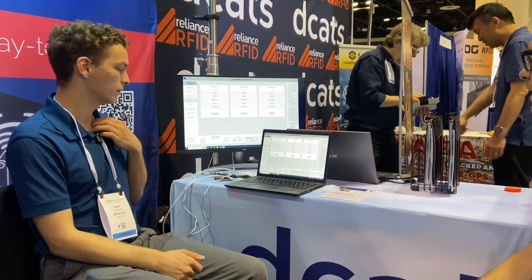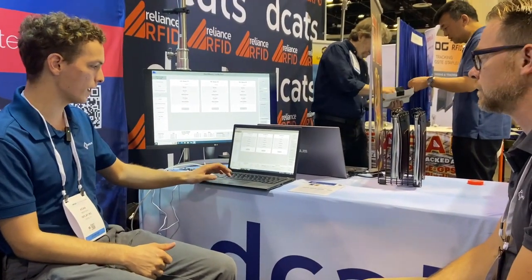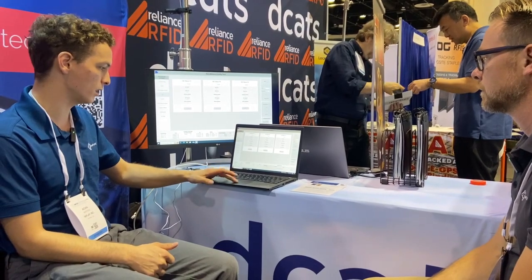That's really neat. So what sort of ranges are achieved with the NanoBeacon? In terms of the wireless range, what's expected? What are the customers doing? Yeah, so for range, we have the ability to change the transmit power level. By default it is at 0. With that you can see 30, 60 feet depending on your environments. You can boost that all the way up to 5. With a power amplifier, of course, you can go higher. And with 5 you can see in a line of sight test hundreds of feet maybe.